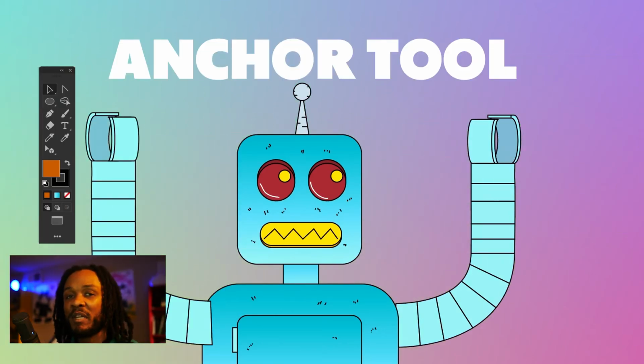The anchor is used to curve and bend your points. Now, let's say that we have a robot, and what we want to do is curve this part to make it look more rounded. We simply go to our anchor tool, and then when you see it's highlighted here, click and pull. If you hold the shift key, you'll get a more balanced pull from both sides from the anchors. You can also use it to manipulate single handles, or you can use it to clear a curve altogether.